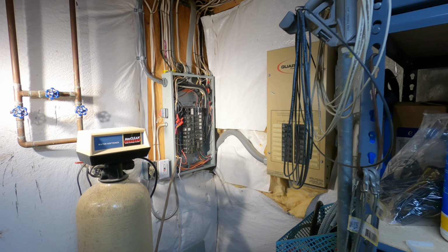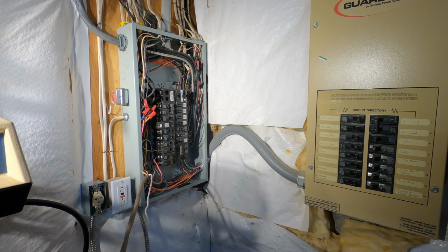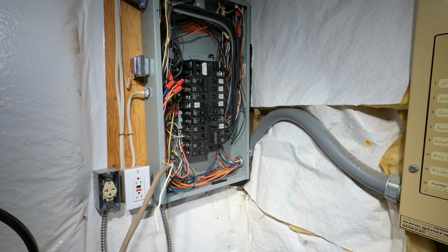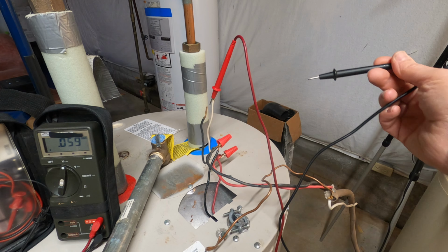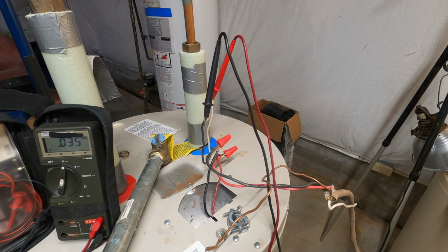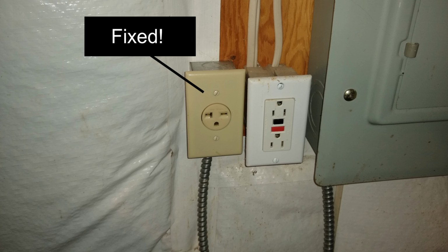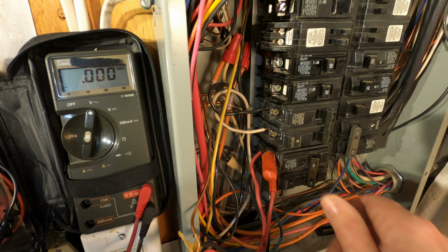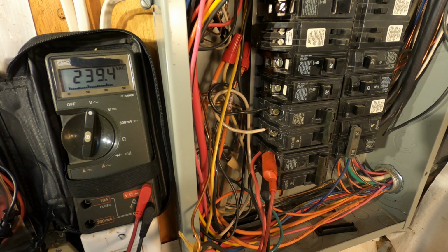I'm using a 40 amp rated circuit breaker for this test. It's the lowest rated 2-pole breaker I have available right now. It'll be fine for this 5 minutes of testing. I would never do this on an actual installation. I added 2 short lengths of wire at the water heater terminations to use as test points. And that's basically 239 volts. Turn it back off.